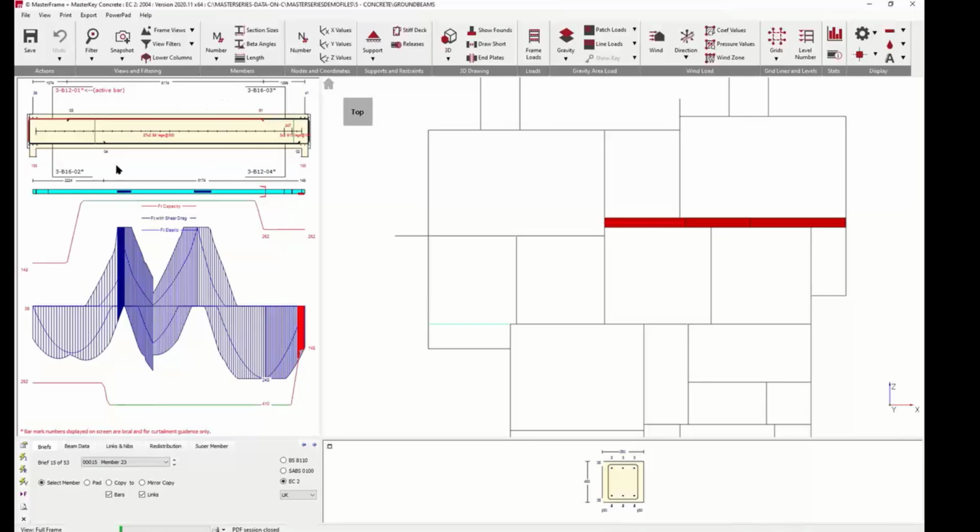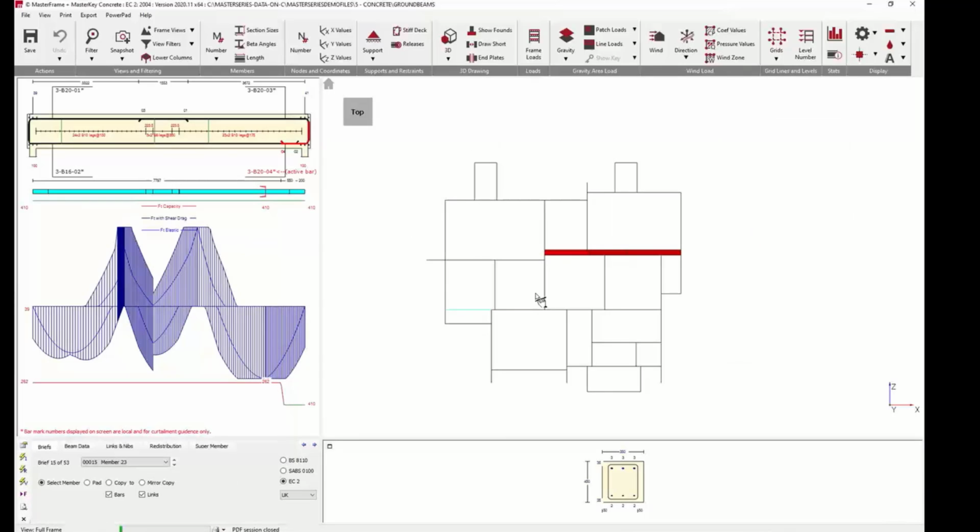So we could turn around and specify very straightforward how you want the bars lapped up. Now I'm just going to drag that across to give it a correct lappage. So very simple. Because of the hugging, we actually do need more reinforcement, and maybe in this instance it might have been more sensible to go for 3 zones, but you have those flexibilities and scopes where you've got very short members together to glue them for curtailment into a more harmonious system.